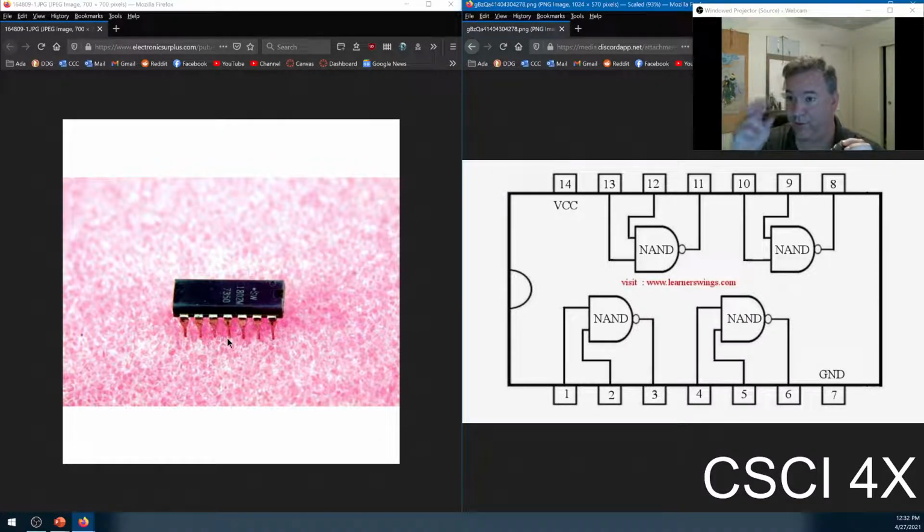What you typically do is you get some sensors, and you wire the sensors. You get these little wires, and you attach them to the GPIO pin, and then your program will read from the sensor. There might be a temperature sensor, or a humidity sensor, or an explosive gas sensor. It doesn't matter. There's sample code that comes with each of the sensors, and you just run the sample code and verify that it works. You breathe on the humidity sensor and see that the humidity levels go up, and you wire the ultrasound sensor to it, and you move your hand in front of it, and it tells you how far away things are.